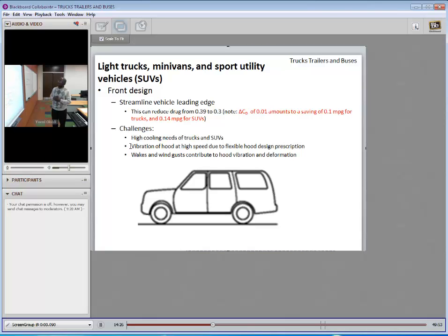Whenever there is impact, instead of the hood shooting into the vehicle, the hood is now required to collapse, falling in a vertical direction rather than a straightforward horizontal direction, thereby saving the passenger's life or preventing the steering from hitting the passenger. That's good for safety. Only problem is, to be able to do this, the hood has become more flexible.